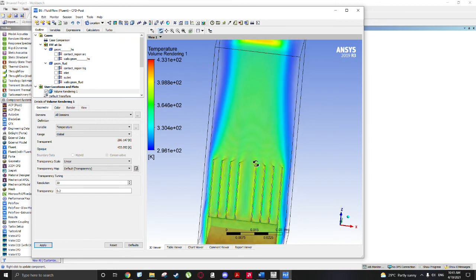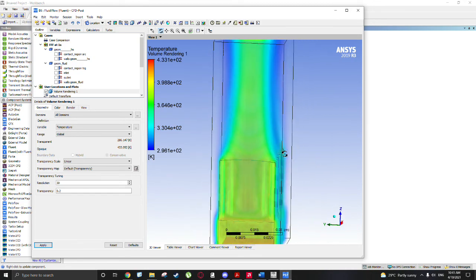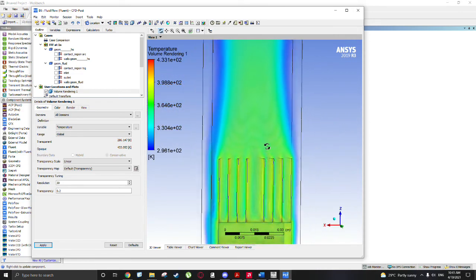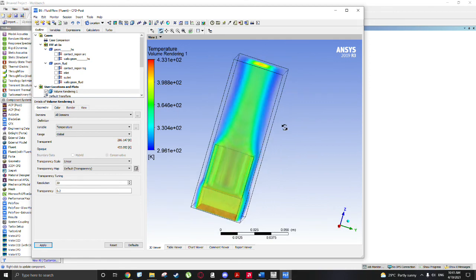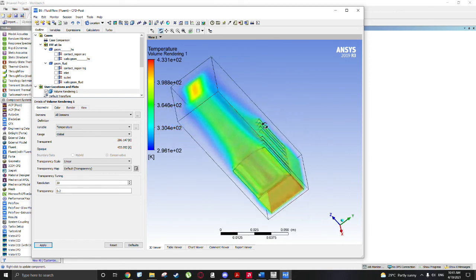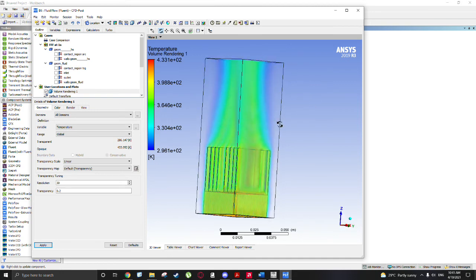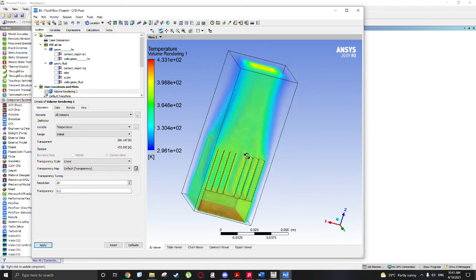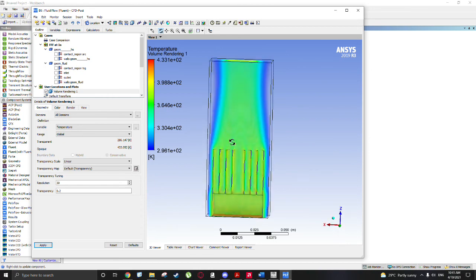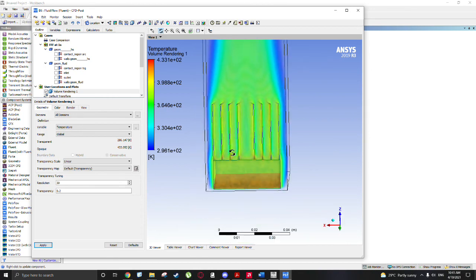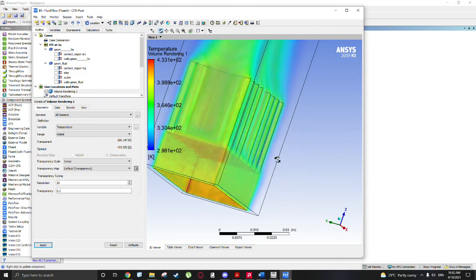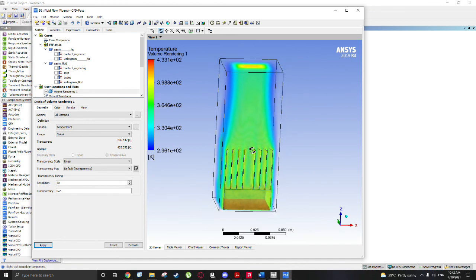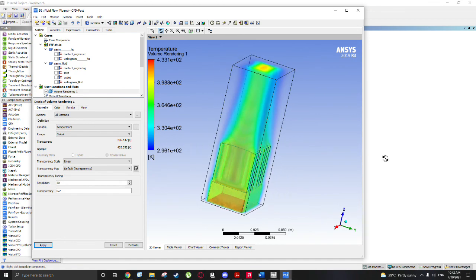Okay, that looks good. We can see in 3 dimensions our inlet is right. We have air coming in. We can see that by the narrowing of the heat region of air, that we have air coming in from all 4 sides, compressing that heat zone of air in the 2 directions. And that's what we'd expect. So our simulation's working, our parameters are set, our interface is good. Happy days. Now you can run a longer simulation, adjust the time steps as necessary, and be confident that that simulation is going to run.